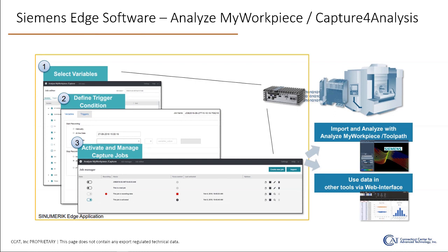The nice thing about the way we're doing this is that we're segmenting out the signal per manufacturing operation. In other words, for manufacturing operation 10, let's say we're going to produce 20 parts, 100 parts, in that particular folder in the Edge device, we have a folder for manufacturing operation 10, and we're going to have as many different data collections as the number of parts that we ran. So the data is already segmented, and we don't have to do that via code.